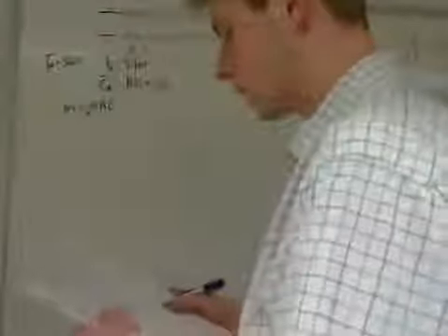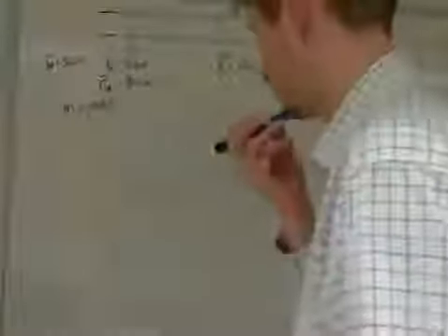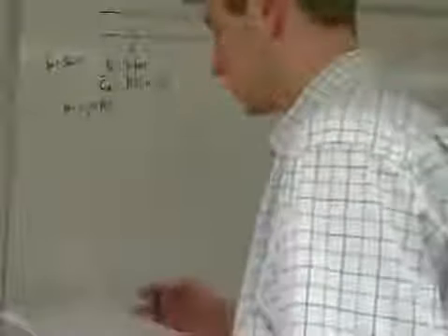And the statement of mass continuity is that the mass flow rate is equal to rho A C, at any location, where C is the average value of the velocity. And so at point A and point B, both rho and C are different, but the value of A and m dot are the same. So part A, we need to find out what the density of air is.